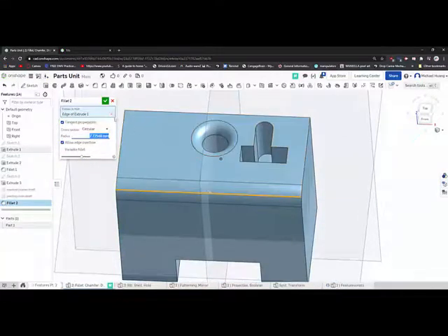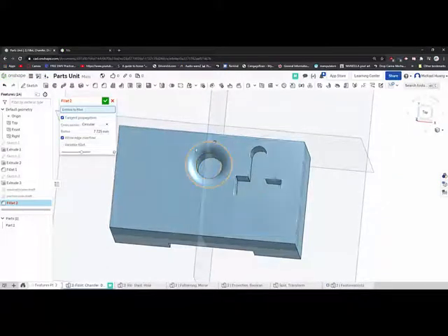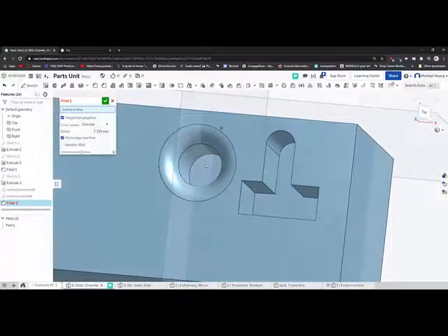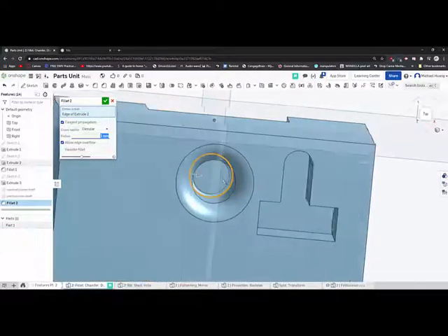Okay. So over here you can see I've selected this circular extrusion, and I've selected the edge and made it filleted. I can do that with the inner edge as well. Oh, sorry. I think the radius is a little too large for 1 millimeter. There you go.